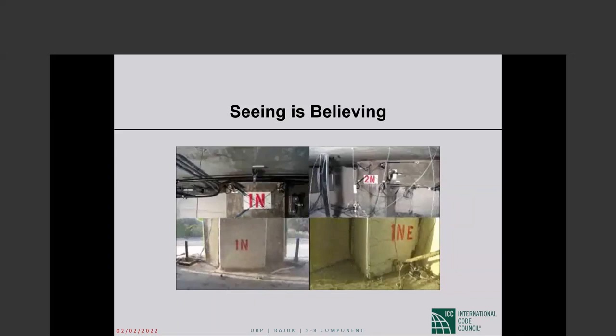It's probably closer to that, but the best way to look at it is that you are cutting off the ground motion. In the absence of the slip that takes place, the motion imparted to the structure would have been much higher than it would be if you have the isolator. So the R factor of the superstructure doesn't change.